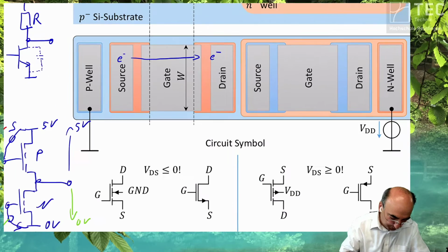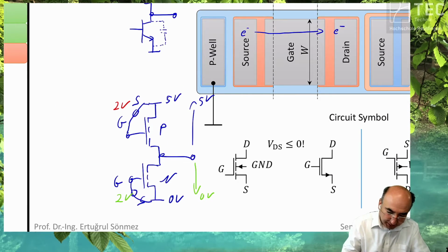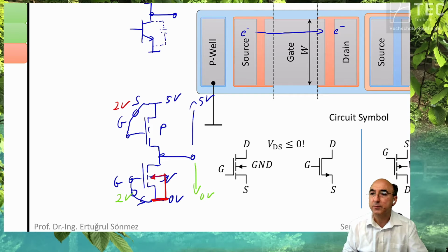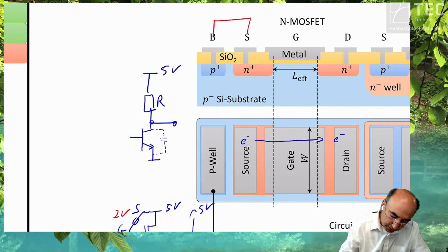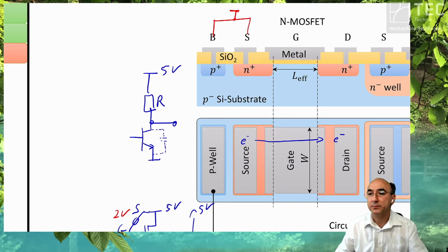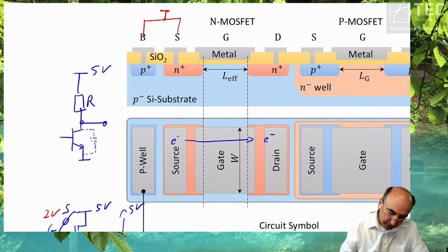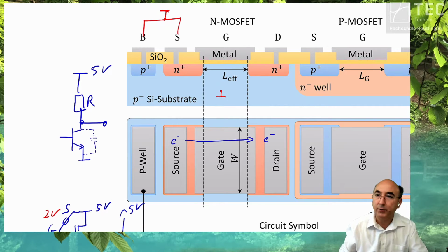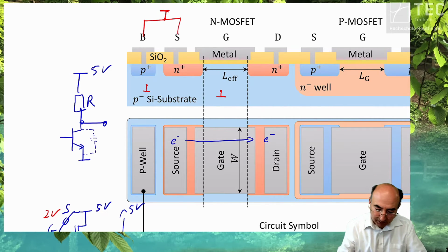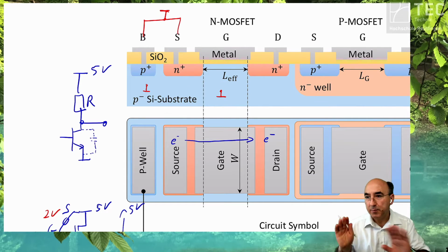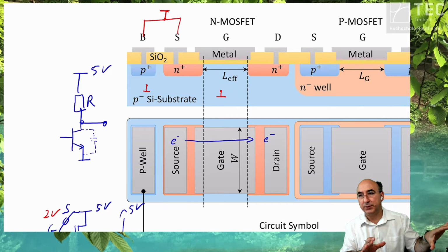And usually, let's go to the circuit diagram. And usually, you contact this bulk to the lowest potential you have in your circuit. Assuming you have here a shortcut and this one is the ground. Therefore, you can say the bulk is connected to ground due to this contact area. In reality, you have a certain potential difference, yes, but we neglect this potential difference, okay?